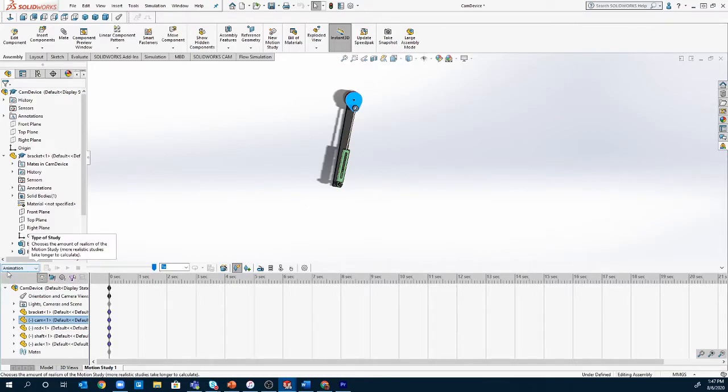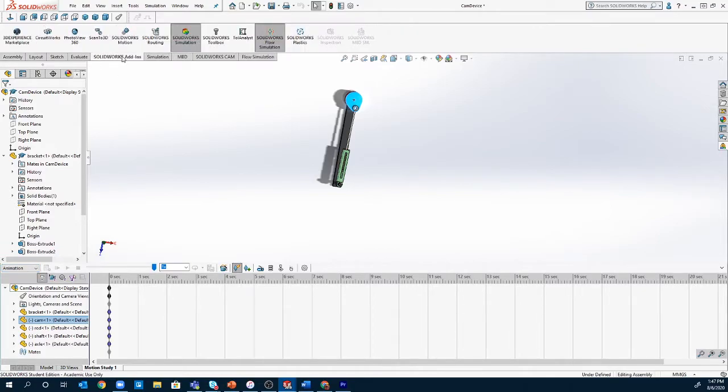And the first one here says Animation. We can pull it down and we see that we have animation and basic motion. The problem with these two settings is that they ignore most of physics, and therefore if we attempt to model how things really work, they're not going to be very realistic. To fix this, we can go to our Add-ins tab here in the ribbon, and we can turn on the Solidworks motion module. By doing this, we can now do computational simulations of motion.